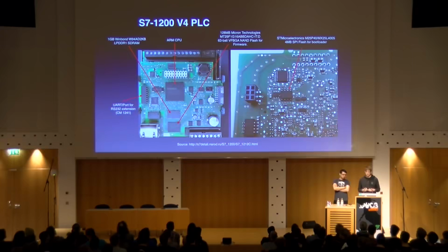And what you can do there is use a special instruction which resides in the ARM instruction set, and you can decode the different bits on it, which we did here, which you can see here for reference. So if you really want to know what's going on, you can take apart those bits and make sure you're actually working with the hardware that you expect to be working with. So here's where we come to the memory part of the hardware, and this is where I leave you over to Ali. Thanks. Now that Tobias unboxed the PLC for us, I'm going to talk about quirks and features in the PLC.